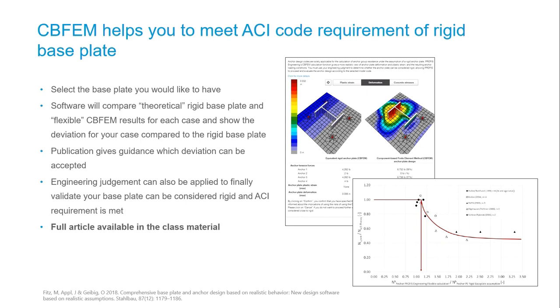On the left-hand side, the theory, rigid base plate. And you can even see it with the distances of the colors changing, right? It's a very linear approach in the stresses and so on, in the deformation. That's good. On the right-hand side, you see now really the realistic behavior of your selected size and thickness. Anchor bolts play a pretty important role. And then you can compare the anchor forces.